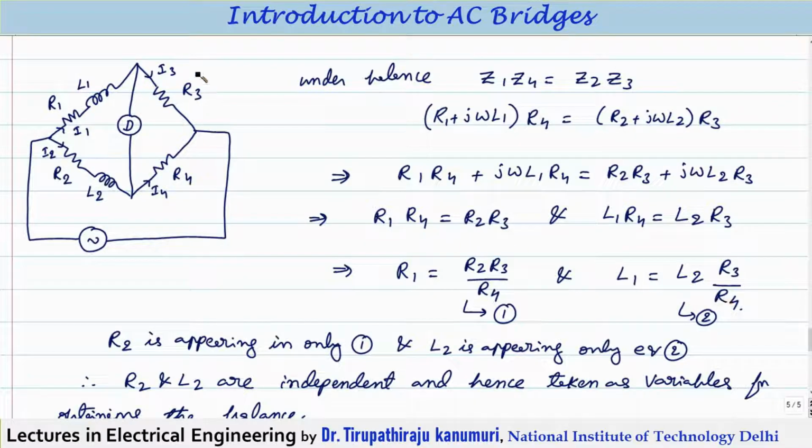You may get the doubt why I have taken constant resistors here, why not some capacitor or some other components. You can see that because I have taken it like this, in all the equations there is no term of frequency. That means these equations are independent of the frequency. That means they are not affected by any type of harmonic components or the frequency components. So that is the advantage of designing the circuit like this.